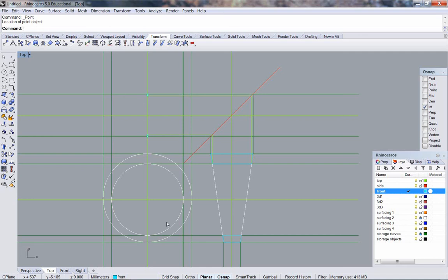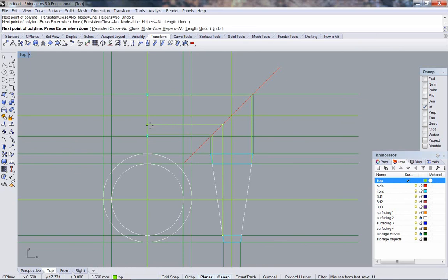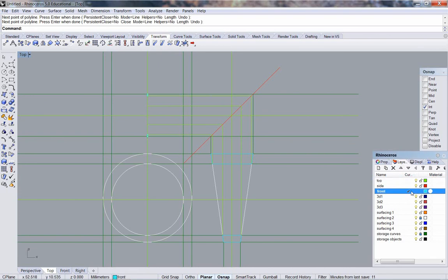For the bottom, once again I'm going to have a dimension for the wider part of the section and the narrower. Construction line straight up, intersect miter line, intersect center line, straight up, using shift key of course to lock ortho, intersect miter line, intersect center line, and my reference points.